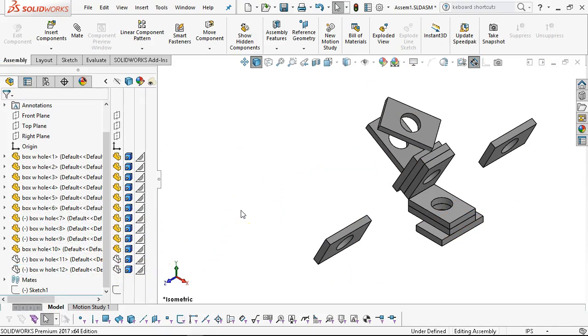Or the pitch. So if you're dealing with standard, so imperial, inch, whatever you want to call it, I always use the example of the quarter 20. It's either 20 revolutions per inch or 20 threads per inch. And if you go to pitch, 1 divided by 20 gives you 50 thousandths.